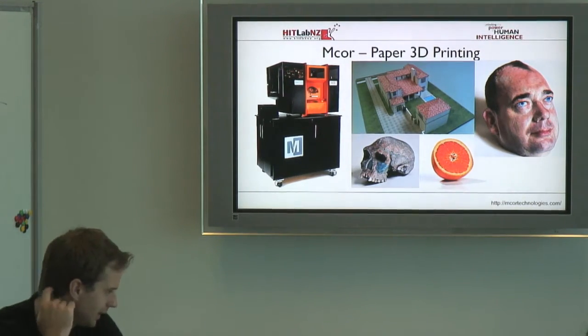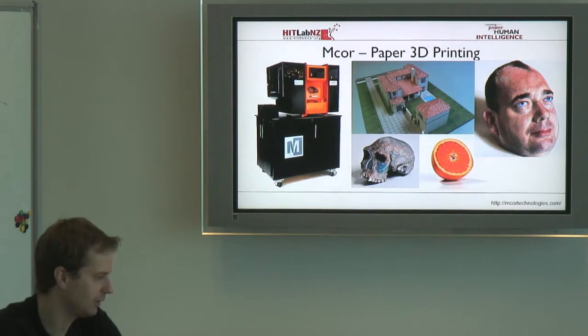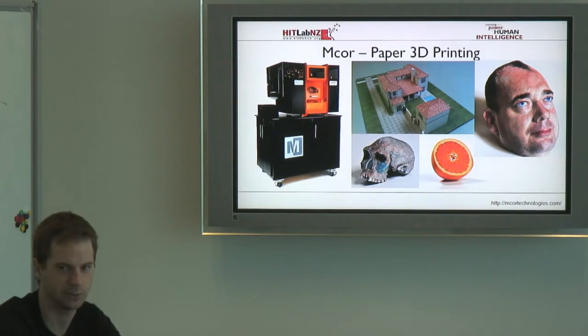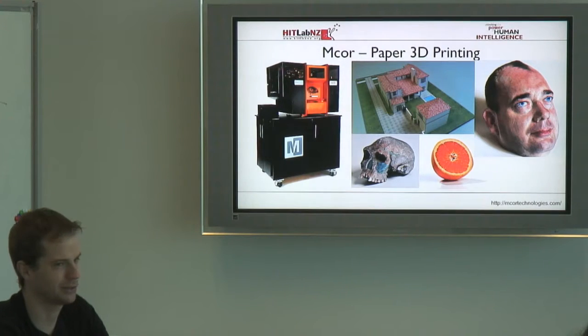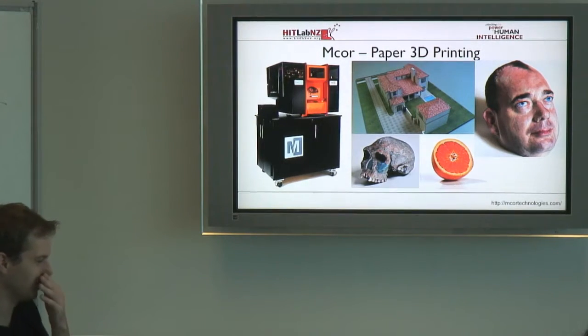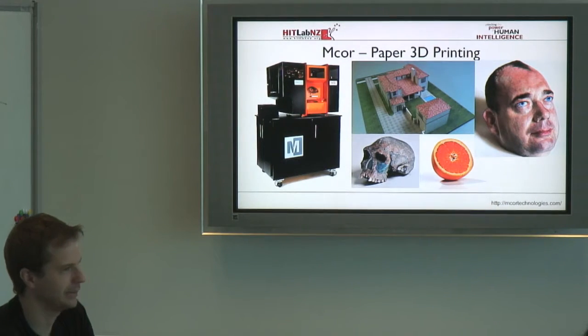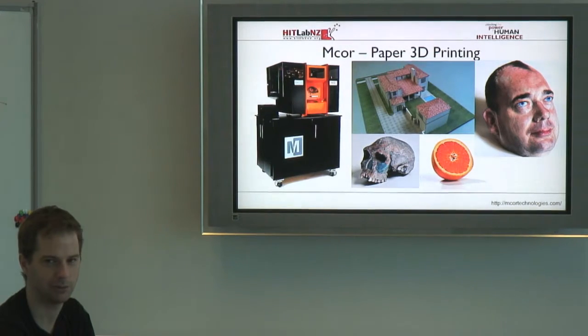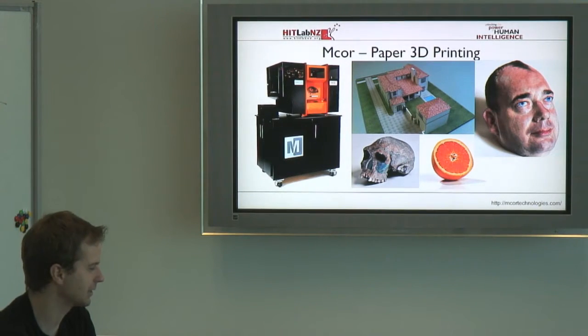With fused deposition modeling, you can print in color, obviously, if you have multiple filaments going into it. So there are various 3D printers which will have 2 or 3 filaments, which allows you to print in one color and then print in another color. And you could arguably mix the colors a little bit to get somewhere in between them, but it's not that easy. On the peachy one, they're talking about how there's 8 different colors, but the color you get is the color of the liquid you put in there. So it's not like halfway through a print, you can say, oh, I want the other half to be this color. And selective laser sintering is kind of the same.